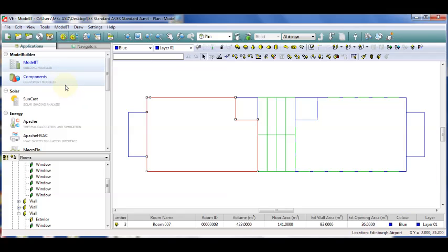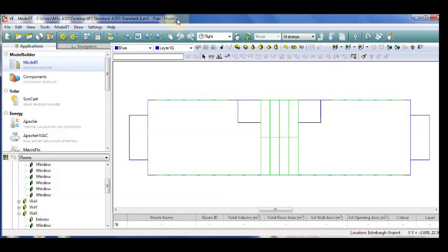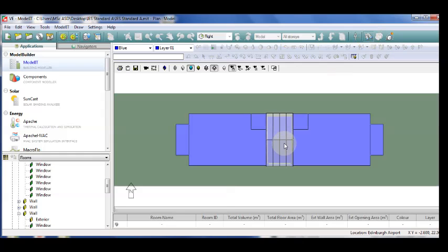So that's how you would change the location, and I'm sure you'll have plenty of use for that in the future as you look at different climates. One more thing that is very handy is to be able to view your building, where you can scroll around the views a bit easier, using View, Model Viewer 1 and Viewer 2 over here, which have slightly different things. Really easy to click on the binoculars to get Model Viewer 1.